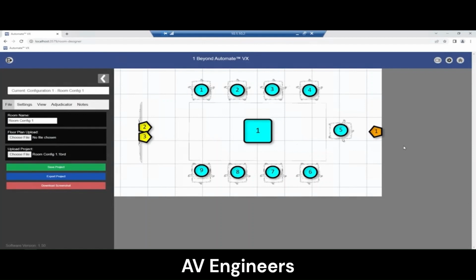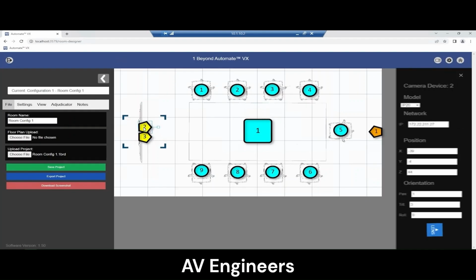It is important to make sure that your cameras are coming in on the correct SDI inputs. The numbering scheme of your cameras in your room design should match the SDI input that each camera corresponds to. For instance, Camera 2 and 3 at the front of the room in this example should be fed into SDI inputs 2 and 3 on the back of the VX system. In order to confirm this, we can look at Wirecast.